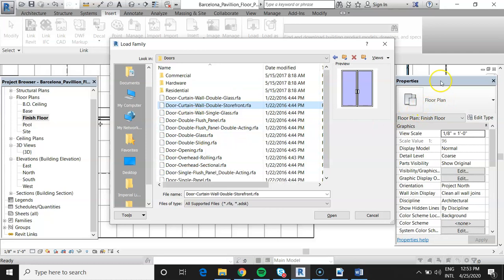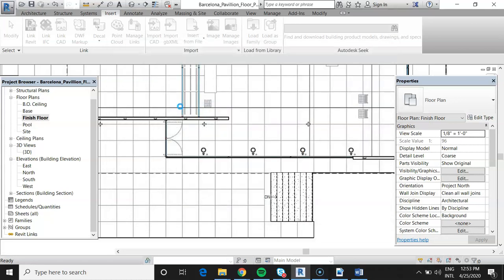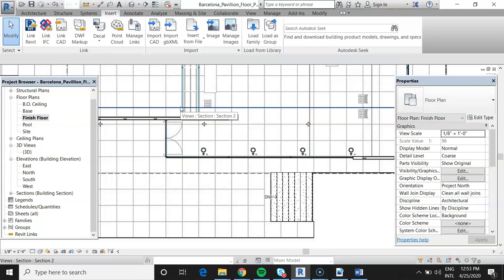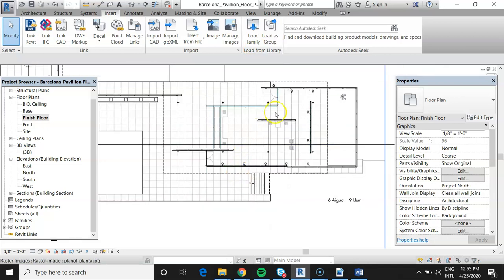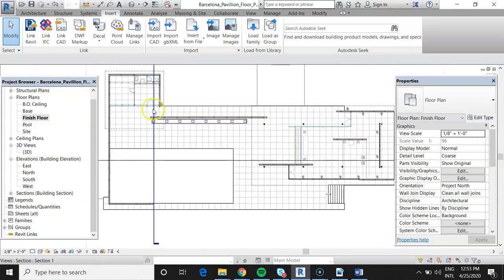So all these things you might not find, again, when you go to inserting doors, in the property box. So there are things that are in Revit, but not specifically in your project. So that's what we're doing. We're digging into Revit to move things into your project. So here's a double door. Let's double click. And you see the thing churn, kind of just blinked, and we know that it's in. I believe there's a single door on the other side. Nope, double door there. Some single doors over there.